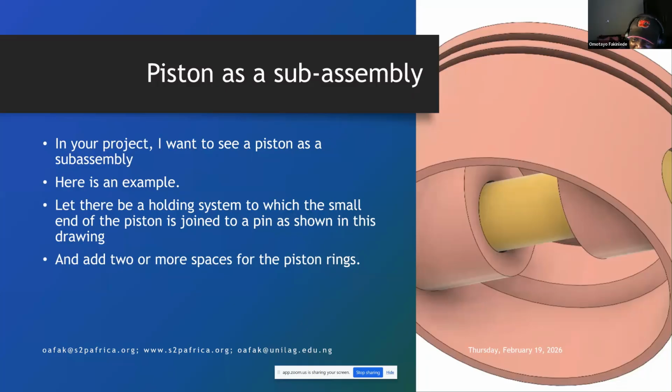You can see that inside the piston, the rigid part holding the pin for the connecting rod is very strong. If you cannot do that with a single feature, there are several things you can do here. You can do a solid of revolution, or a revolution and several extrusions before you get there. They can be different parts that are assembled together using fixed assembly joints. So the choice is yours.